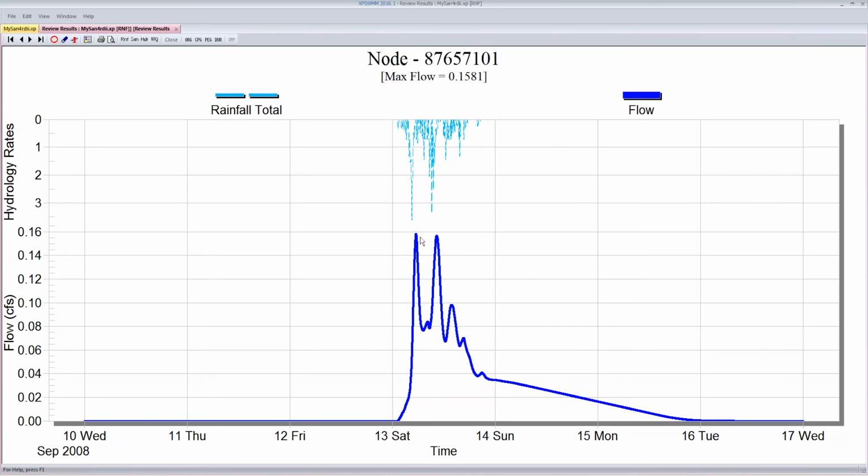And as we calibrate the model, we'll take this estimated maximum flow and we'll compare it to actual meter data. And at this point, we might need to make adjustments to adjust the RDII model so that we're more closely matching the meter data that we get. So there's a lot of calibration that can go on to make sure that we're accurately modeling the impact of inflow, infiltration, the time it takes to get into our system and to have an impact on total flow in the system.